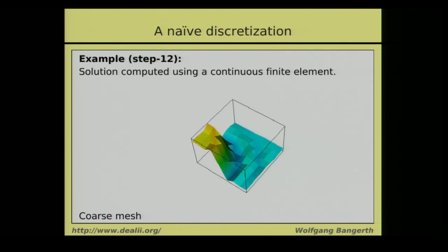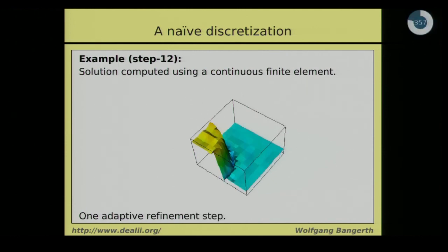You'll see a little better how this initial condition or boundary condition looks when I refine the mesh. So let me show you what happens when I do refine the mesh. This is the coarse mesh, and the next mesh looks like this. I have an adaptive mesh. You can go to step 12 and look this up. If I refine one more time, I get something like this. So you start to see there's 1 here, 0 over here. And again, I have transport of this concentration 1 over here, so it goes out in this direction. My inflow part is here, and the 0 is transported around here. So far, this looks actually quite all right, right?